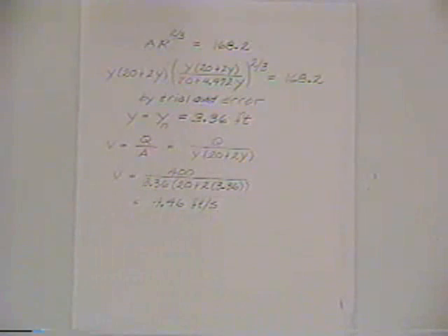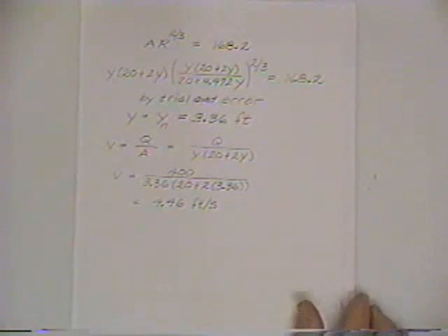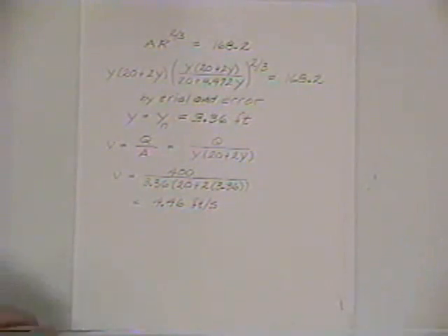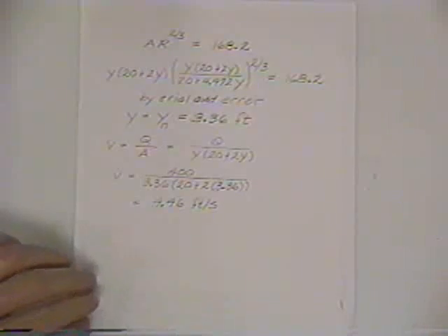And so that's basically using the Manning's equation. The geometry is a little more complicated in a trapezoidal channel. A rectangular channel simplifies the geometry. And so the problem can be given for a given geometry, compute the flow rate, or vice versa, for a given flow rate, compute the geometry.